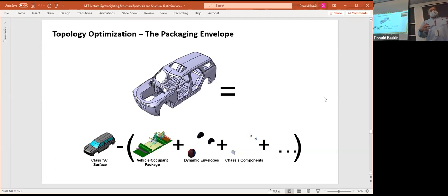The actual packaging volume needed for the wheels is complicated because the wheels are going up and down, and they're also turning in the front of the vehicle, and sometimes in the rear. And so they have these things called beehives, which are the full envelope of possible positions of the tire. And you have to subtract that for things like the battery, the suspension, the gas tank, the sunroof. Okay, this is what's left over. These are all the places that we determined you could have structure within this SUV.